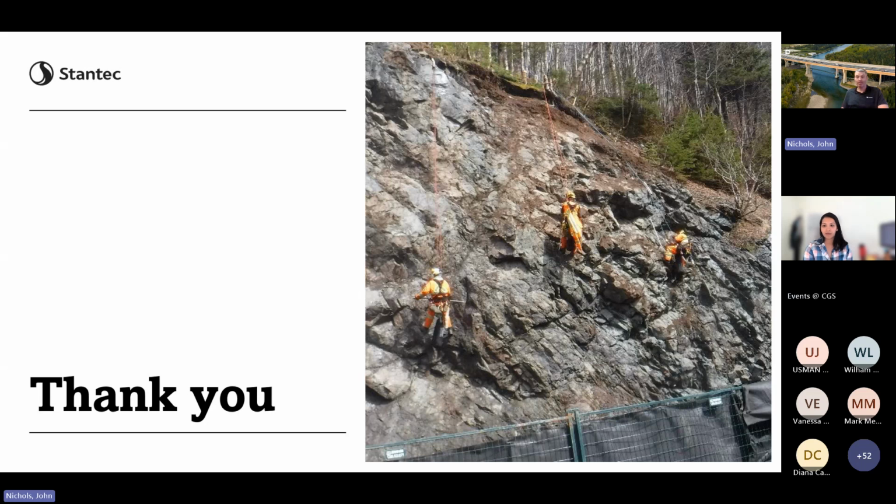Typically, it gets refusal in rock. The only method we use for coring is diamond drilling. Having said that, if you collect a split spoon sample and it's cemented soil, you may want to consider rock properties. But no, we don't use split spoons in rock exploration.